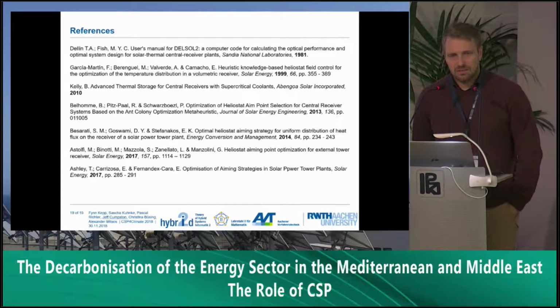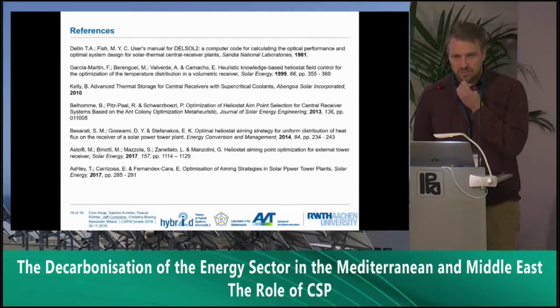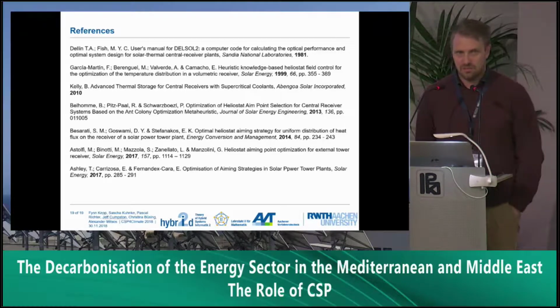And the consequences of exceeding that or getting particularly high flux spikes is a failure of operation. So you can reach your material limits, and you can damage the receiver, and that can turn into a runaway effect. So if you start to damage your receiver, then you can change the function of the receiver, and it can lead to problems. So I hope that answers the question.